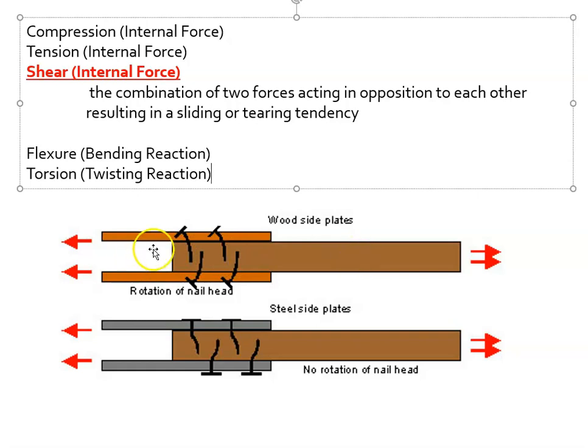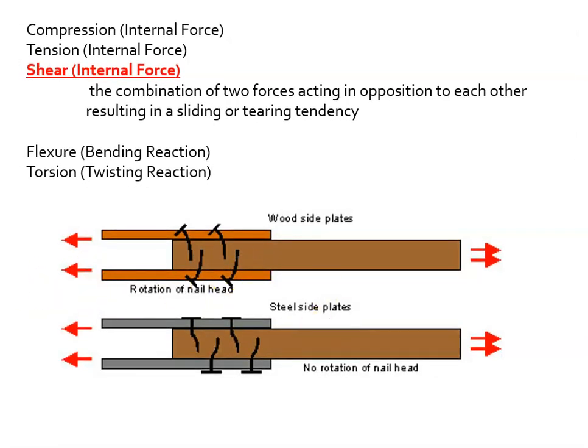Part of them is being pulled in one direction, parts being pulled in the other, and the fasteners are being sheared. This just goes to show that in a wood plate, the fastener would be bent more gradually. Whereas in a steel plate, that nice bending isn't afforded, and really at where the connection takes place, that interface, it's going to be a more sharp kind of shearing action. Okay, but again, the specifics we're not so interested in.